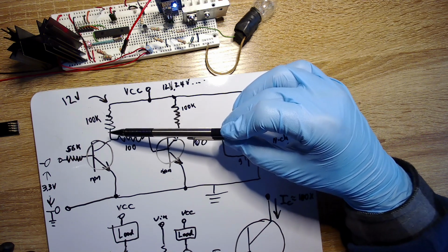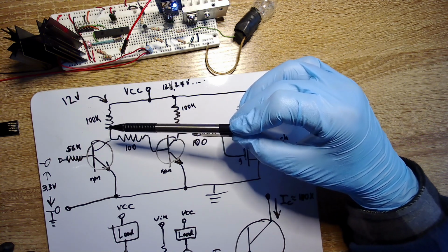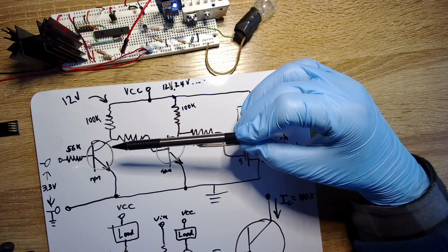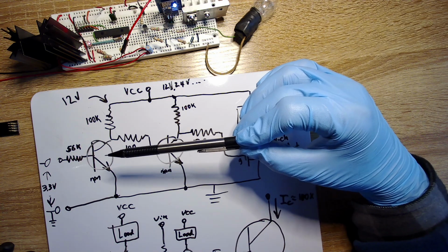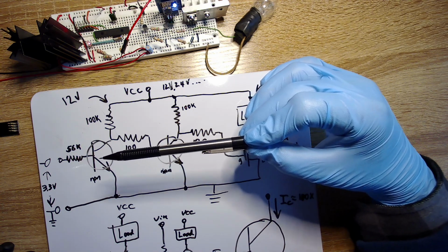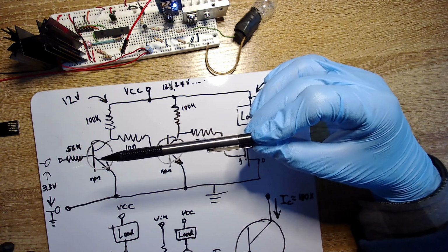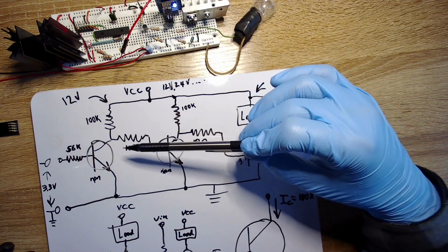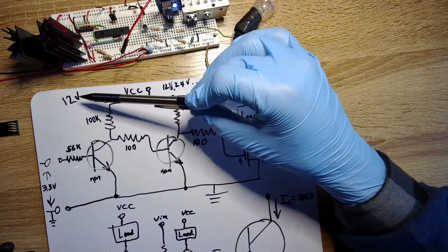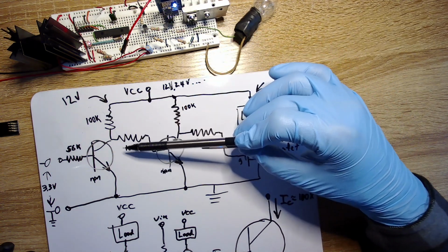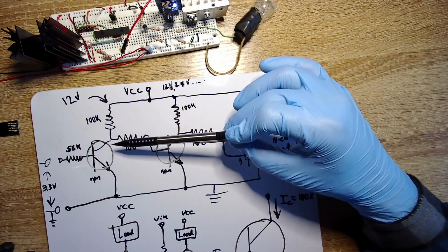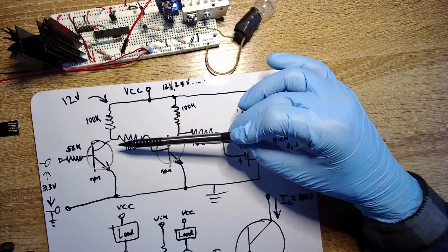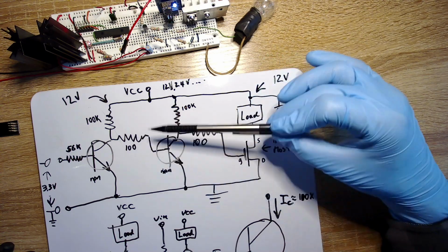Now, this is operating in a switch mode, right? So you're going to be thinking in simple terms: full on or full off. There are a lot of interesting circuits out there, but many are about amplification of AC signals. A lot of them don't even say that we're talking about AC signals, but that's where you see a lot of capacitors and transistors, and they're trying to bias the voltage sort of in the center. Let's say we're using 12 volts for an AC. This is not the case here, but just to differentiate, you'll see other circuits where they try to bias the voltage right in the middle, around 6 volts, so that you can swing up and down.